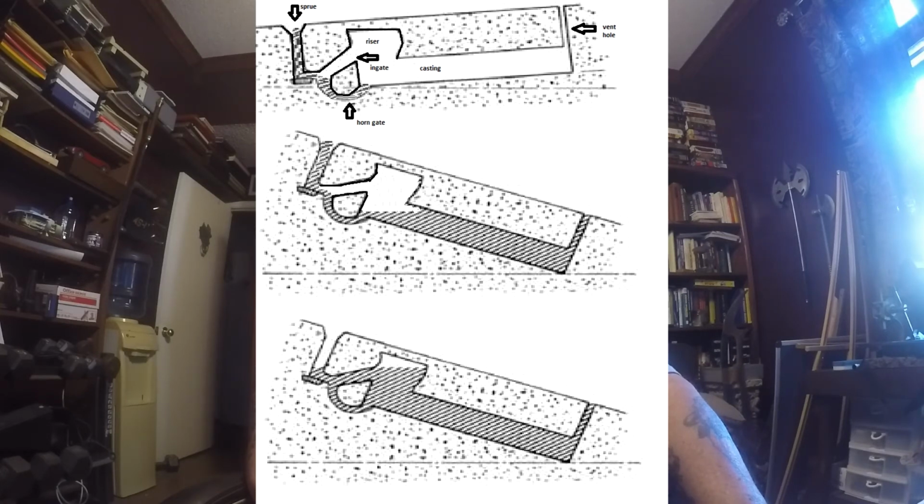And at that point, you could just set it flat, because you've already done what you intended. You've already started the solidification process at the far end of the casting, but it doesn't show that here. But it's a good way to absolutely make certain of your directional solidification by way of mold manipulation.